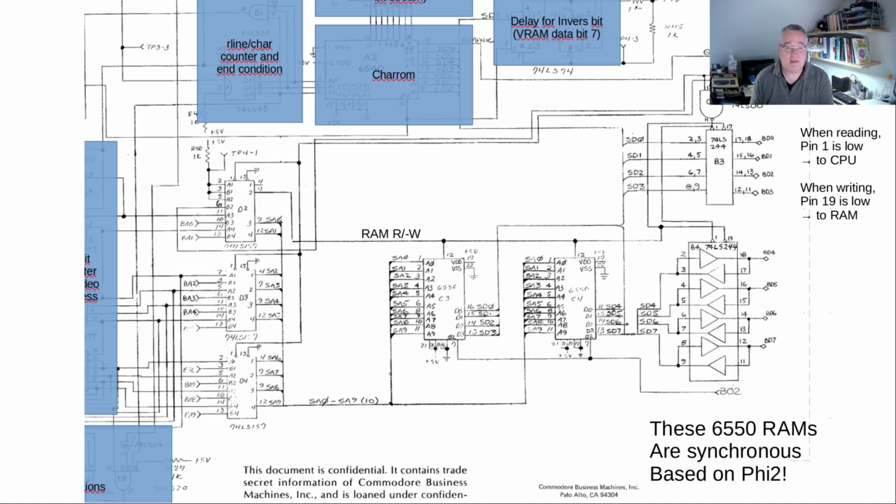And when we have the RAM read minus write, only the CPU writes. Once we have a write signal here, this goes to the other side of the buffer, and then pushes the data out, takes the data from the CPU into the RAM. As I said, interesting here, there is this connection with selecting the E address space, which doesn't matter because it's always selected here with the video RAM.